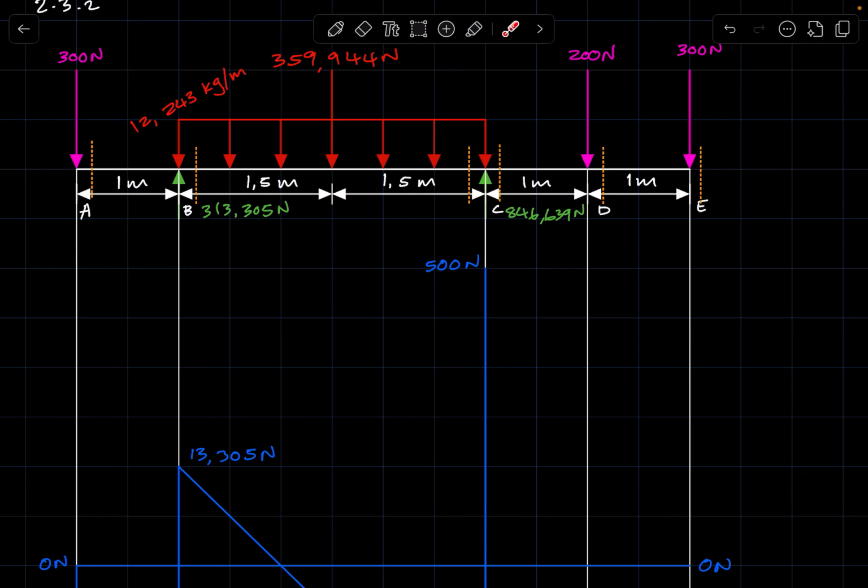After getting this, it means we are done with shear forces at this critical point. Now we move on to the next critical point. Remember, here there is no UDL. Because there's no UDL, you draw a line going straight across. Then we consider forces on the left of this section, between the current section and the last section, which is this negative 200.